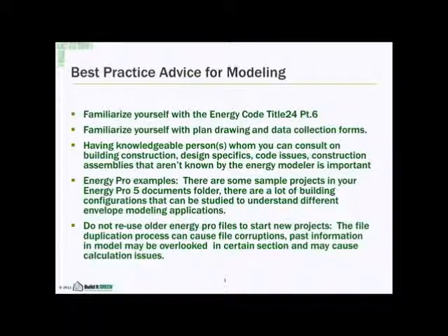And it's always a good idea to not reuse your old EnergyPro files as templates. I've seen file duplication cause some errors and file corruptions, and past information always gets overlooked, and it causes certain loads to be wrong, depending on if it's a fan or heating or cooling or windows. I've seen it give calculation errors and cause buildings to not comply. So if you start from scratch with a new file, it's always better, and just give yourself time to build out a full model.